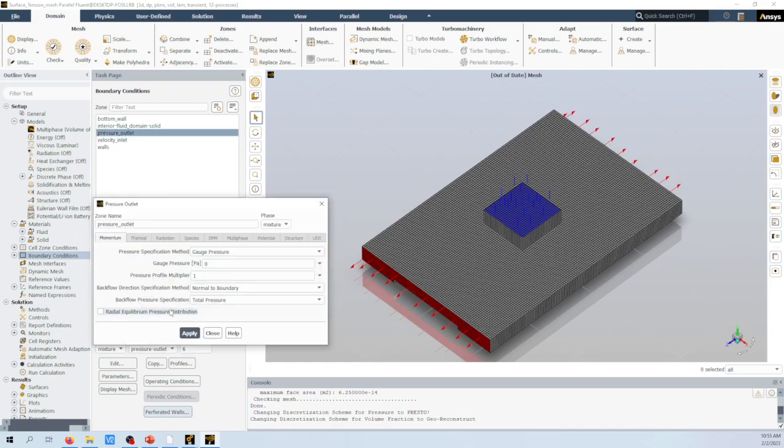we can go to pressure outlet. This is your typical setup now. Velocity inlet, pressure outlet. Gauge pressure 0, we have defined that since we have air in this cavity to begin with. This is an atmospheric pressure condition at this outlet. Now, as the cavity fills, we are assuming that the backflow pressure from the rest of the cavity, the pockets surrounding this outlet, is negligible. So we're just having free flow from the inlet to the outlet.